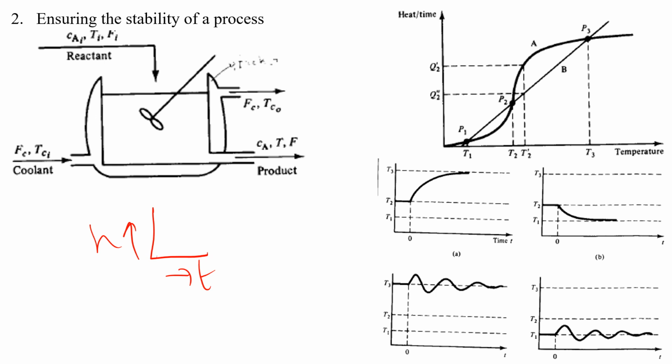The level of the tank should not increase like this, because if it increases like this, overflow happens, or suppose imagine that the temperature is 1000 or 2000. Just imagine if it overflows, or it may cause a problem with the safety of the tank. So this is called unstable. It keeps on moving. So we have to bring that temperature to settle at a particular temperature. So that is called stable. To bring that temperature to a stable condition, we need a process control.